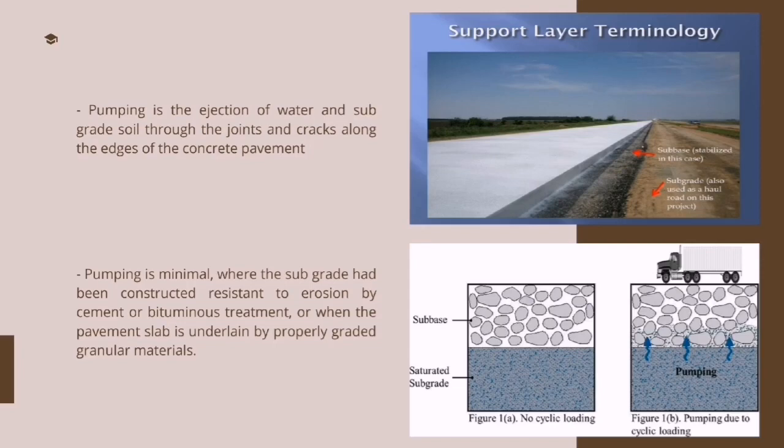With the presence of water on the subgrade and churning it with the soil, a fluid slurry forms that is expelled to the surface. A continued pumping by heavy axle load will flush the soil from beneath the pavement to the affected location. Failure of the joints will be noticed, followed by transverse cracking or breaking of corners. One crack will invite more pumping action and joint failures, and the cracking will be progressive.